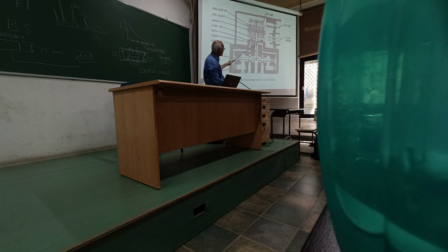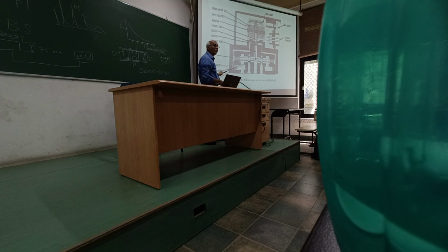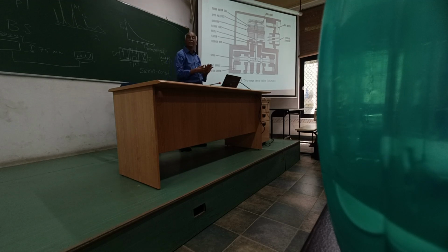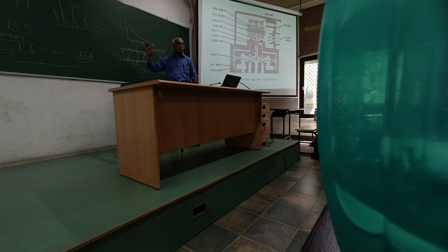So the pressure fluid which is coming here will change the position of this valve, and in turn this valve spool will decide how the fluid flow will be. This mechanism is used to control the system, either pressure or displacement.